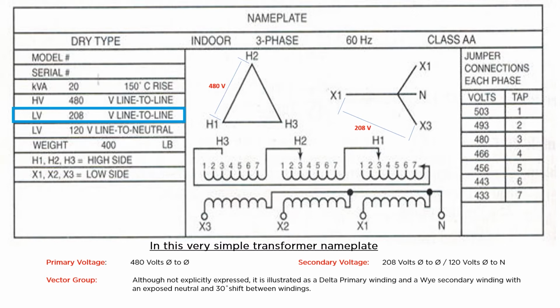If we look at the next piece of information, it tells us that the phase-to-neutral voltage, or the line-to-neutral voltage, is 120 volts. Now, if we didn't have both of those supplied to us, we'll see in just a little bit that we could have calculated one from the other and vice versa. We also want to say that because it's a delta in relation to a Y, there's going to be a 30-degree shift in the relationship between the two windings of the transformer. We'll see that in the next slide.